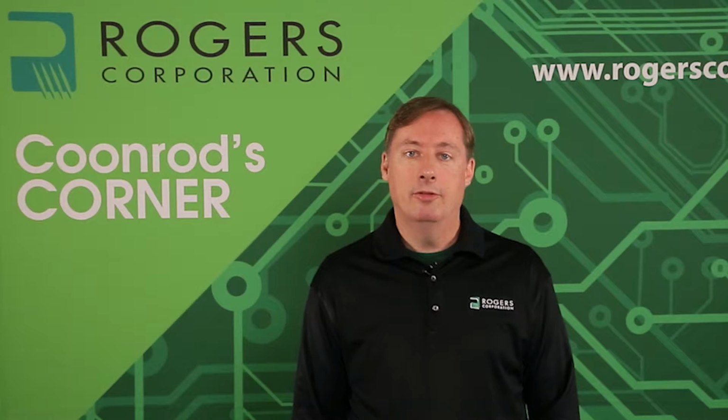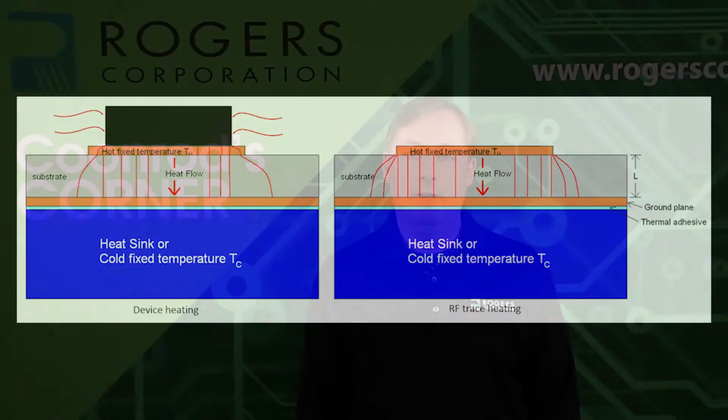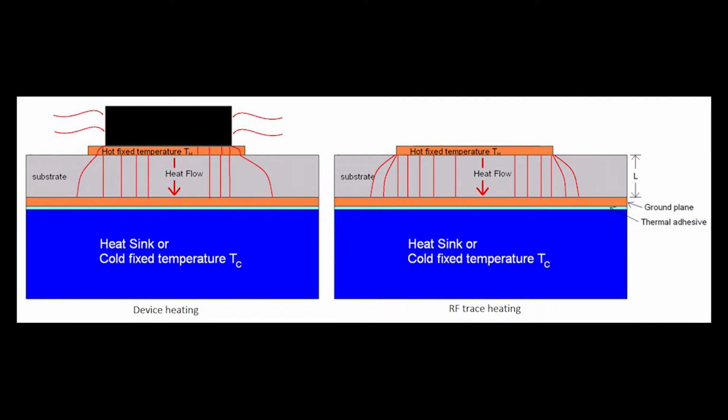In the case of what's important for materials for these two different scenarios, one of them is pretty simple, and that's the case of the device heating. The device heating really is looking at material properties that are simply the thickness of the substrate and the thermal conductivity. The thermal conductivity, of course, being higher is an important thing, and the substrate thickness being thinner is an important thing for increasing heat flow.